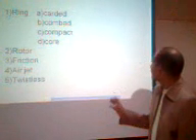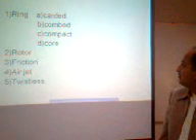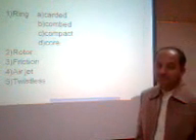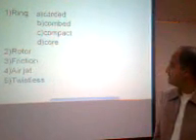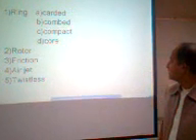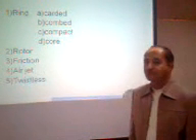Looking at the groups of the spun yarn, we can have ring yarns, rotary yarns, friction yarns, air jet yarns, or twistless yarns. The ring yarns have further three groups: the carded, the combed, and now the compact and the co-spun yarn. Here is the layout of the spinning process, which is used to produce the ring spun yarn.